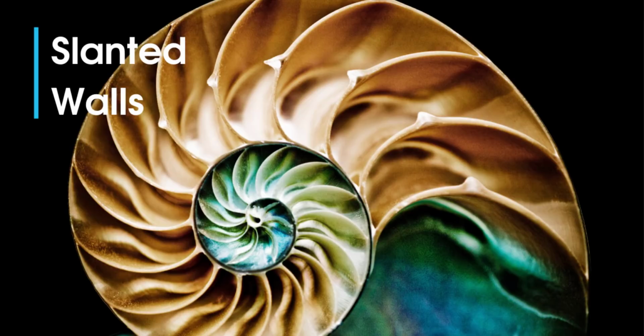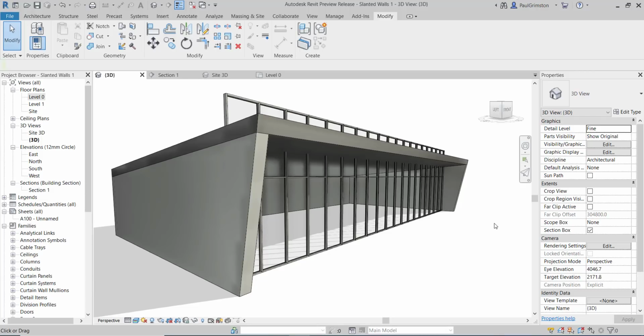The next new feature we're going to look at in the 2021 release is the ability to create slanted walls. In previous releases, the only way to achieve a slanted wall was to model a mass object and then use the wall by face or the curtain system tool to attach it to the face of the mass. This meant having to keep and update the mass for any changes required in your model as your design progressed, and was always a bit of an inefficient workflow, having to go back to edit the mass, save that, reload it, and then update the actual walls and things that were attached to it.